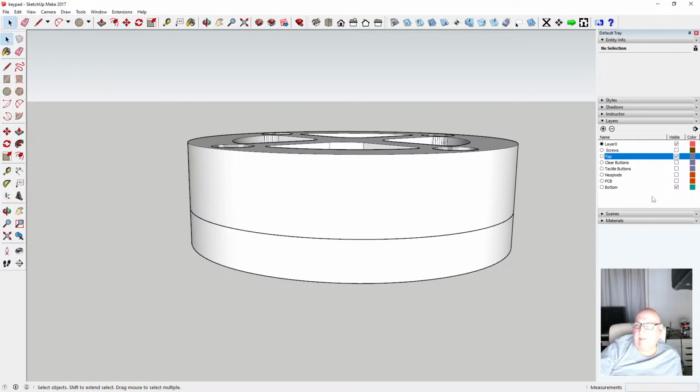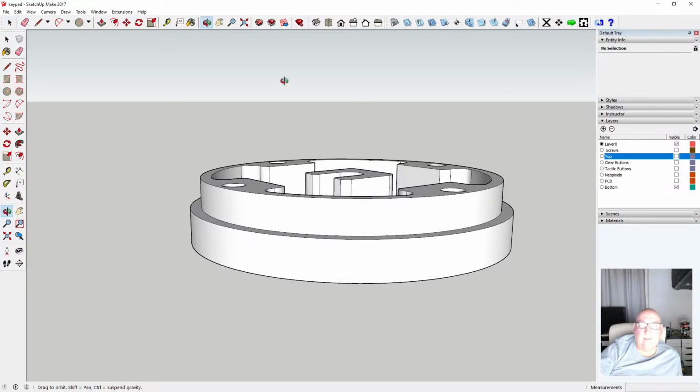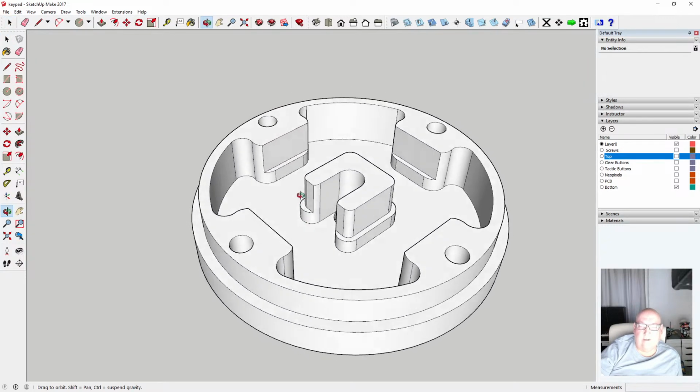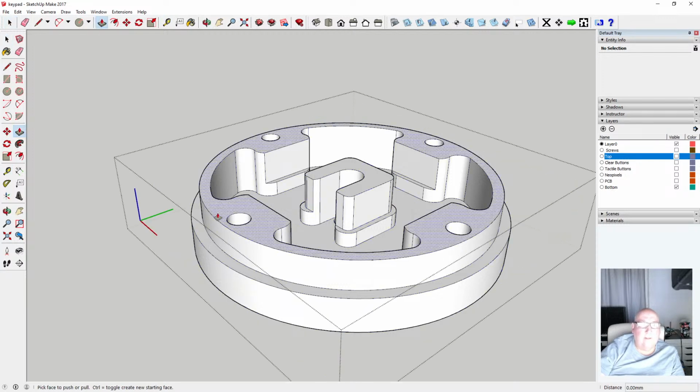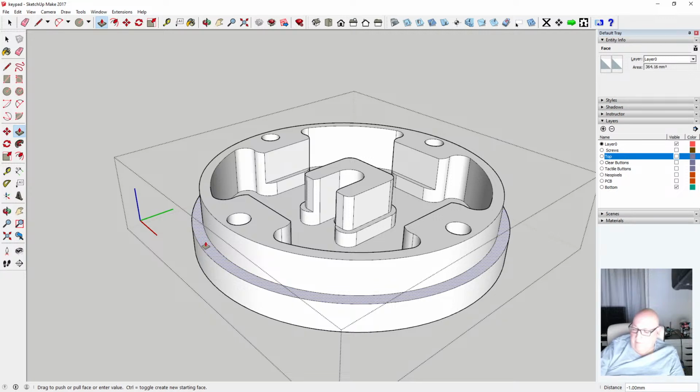Let's just do it. Let's hide the top a minute. The outside is not going to affect anything because that's a different size anyway. Is that a different size? So we've got 3mm there. Hang on, let's find out what we've got here. That's 7mm. 3mm, so 2mm bottom base. Yeah, so it's different anyway, because 3mm and 2mm is 5mm, and I've got 6.5. So let's just alter this by 0.5 of a mil.